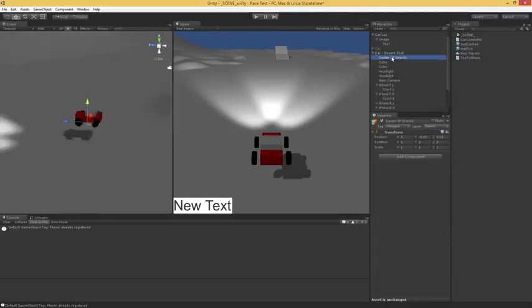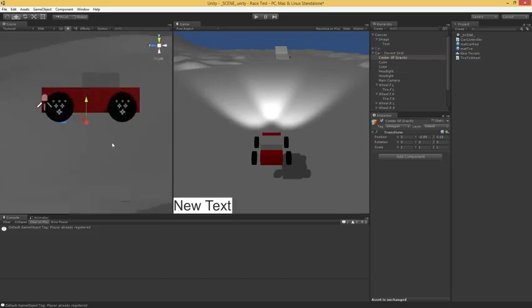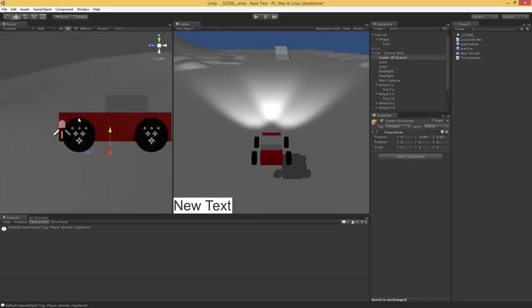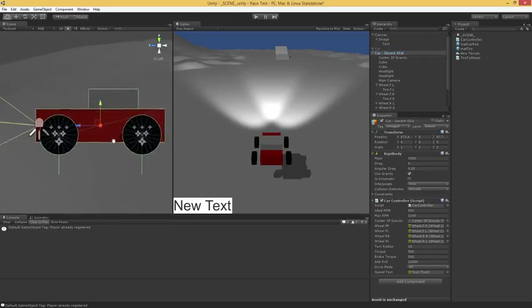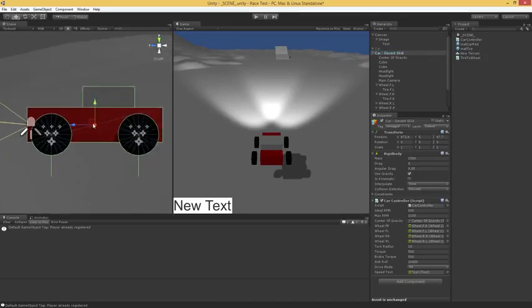I've got the center of gravity here. This is one of the things that you use to sort of fudge the rolling system. Now, by default, if we didn't set a center of gravity, the rigid body component, right over here, will use all your colliders and figure out a midpoint for your center of gravity, which would end up being around here where our transform is. Actually, it might even be a little bit higher than that. And that's not really realistic because a lot of the top part of a car is empty. Most of the weight is at the bottom of the car, and specifically towards the front where the engine is. So you've got all your axles and everything like that near the bottom of the car, and those are really, really heavy. So your center of gravity is probably around here in a car.